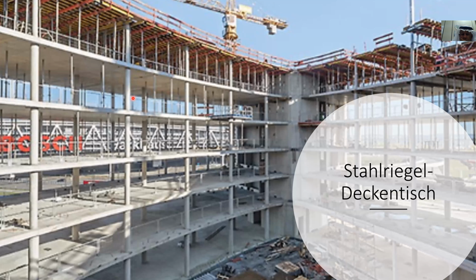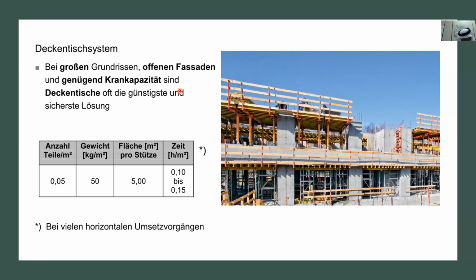You have to have an open facade. Later on, there will be most probably a steel or whatever kind of facade. And this is actually the most economic possibility to make this concrete slab formwork. You need only 0.05 parts per square meter. And the timing, if you can use it several times, goes down to 0.1 working hours.